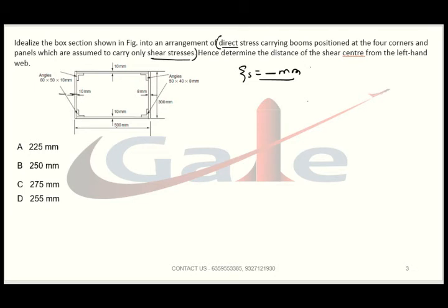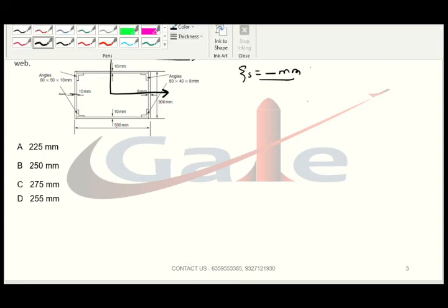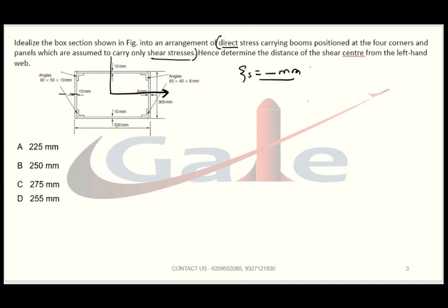Okay, if you try to see, this is a rectangular closed thin wall section and the coordinate will be somewhere here, and the centroid will also be somewhere here of the structure. Somewhere, it is not exactly at the center because thickness is not the same, that means the material present is not the same.